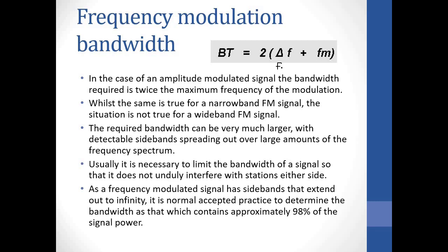So this is 2 times FD plus FM. Unlike amplitude modulation, where it was just 2 times the highest FM, in this case we add the frequency deviation.